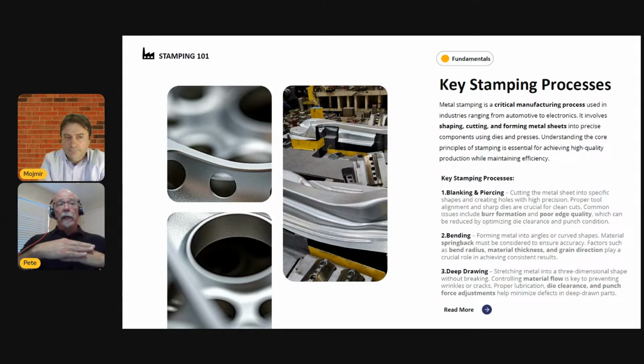As soon as you are hitting home in that condition, your shut height is set. If you have to hit the bend radius harder, or if it's overbent and you have to back off of the bend radius, you have to shim or remove a shim from the bending punches, the forming punches. Do not change the shut height. Once the shut height is correct for the material thickness you are using, that's what it is.